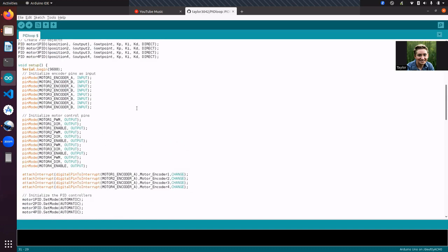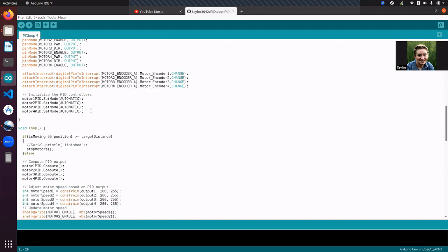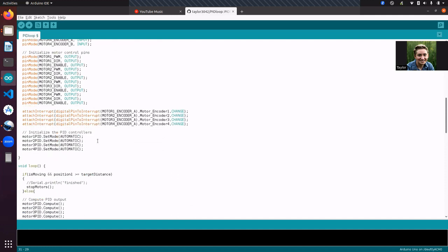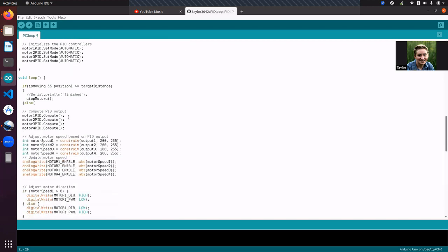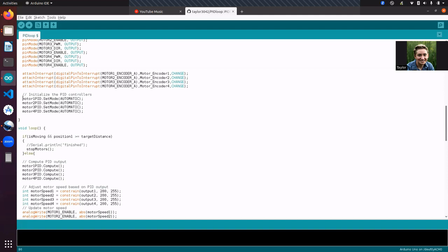And then we're going to want to set the mode to automatic. That makes it so the PID, so automatic obviously just means that we don't manually try to calculate the variables ourselves. It makes it easier so we don't have to do calculus within our code. Or within the code, obviously the microcontroller is still going to have to calculate this, but the other thing that I did notice that I also want to point out before I go further is the microcontroller is a lot weaker than a computer is.